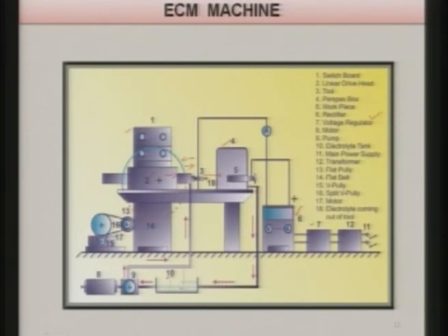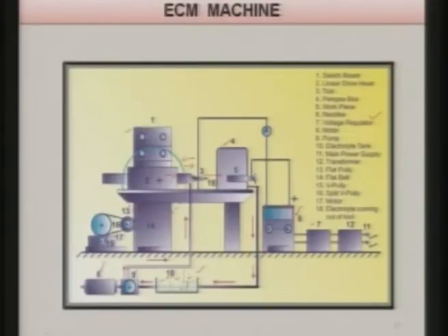8 is the motor, as you can see there. Here this motor is used for driving or running the pump 9, and there is an electrolyte tank 10. This is very interesting to see here, electrolyte tank, it is divided into 3 zones 1, 2 and 3, and in this whatever electrolyte is coming in region 1, and the reaction products which are lighter than the water, they will remain in this electrolyte region 1, and then rest of the electrolyte will pass through the bottom and then it will come into the area 2, and in area 2 again whatever heavy particles are there, they will